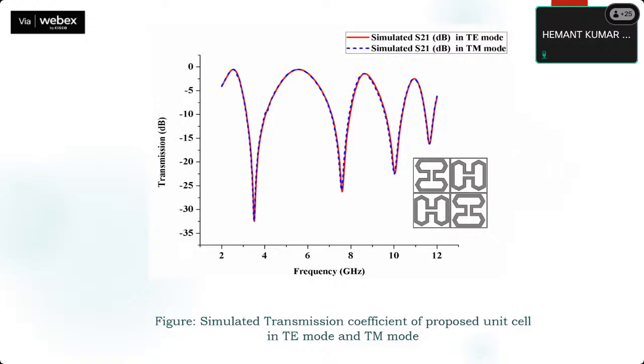If you are placing the FSS in the ground, then you take the equivalent circuit of the FSS in the ground, then your substrate, then the copper, then your patch, then an L element is there, with the C, and your complete FSS structure is there. You have to combine all this.